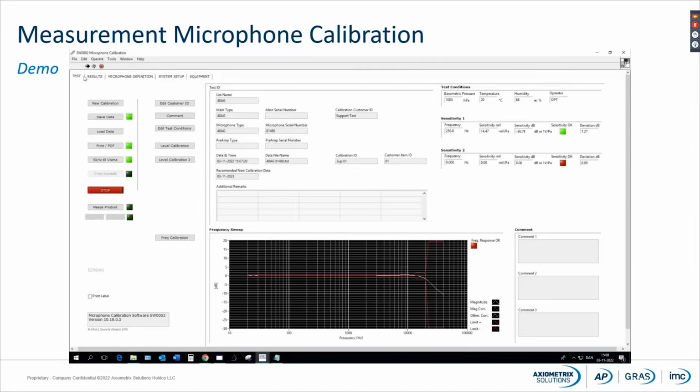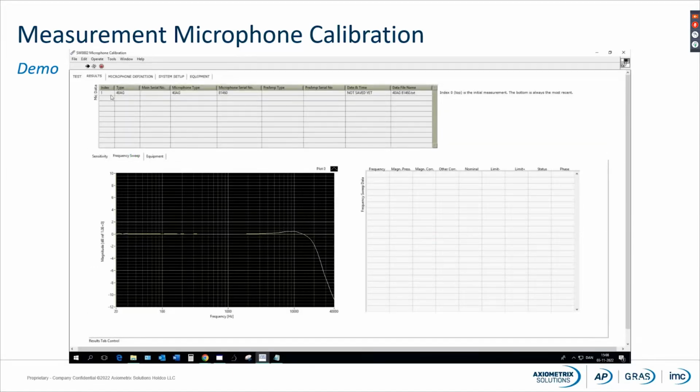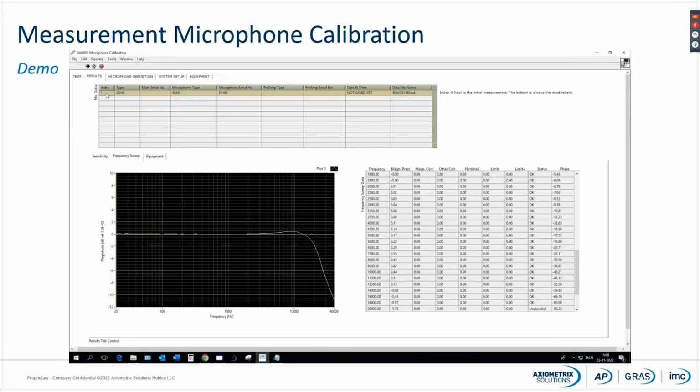I've now done the calibration, and I can, if I would, do an analysis of the result. So I can see the whole frequency range, and I can see at 20 kilohertz, I'm actually touching the tolerances a little. So it's maybe 0.01 dB out at 20 kilohertz. So it is actually nothing.